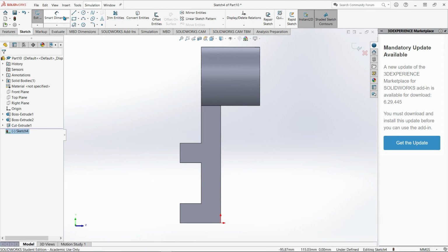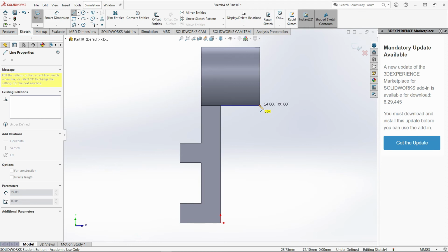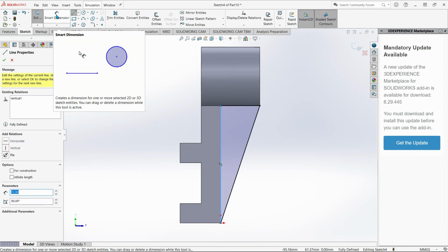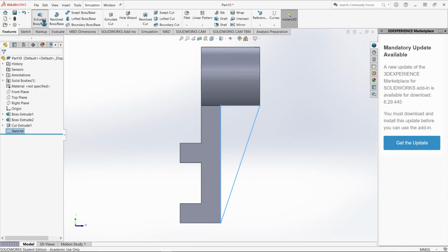Now as you know the plane is inclined and we know the edges of the incline, so it's something like this. So I'll just make this particular solid, and it's already fully constrained, so even if it is not constrained, you can just merge the points, it will be constrained. So we'll exit the sketch, go into features and say extrude boss base.